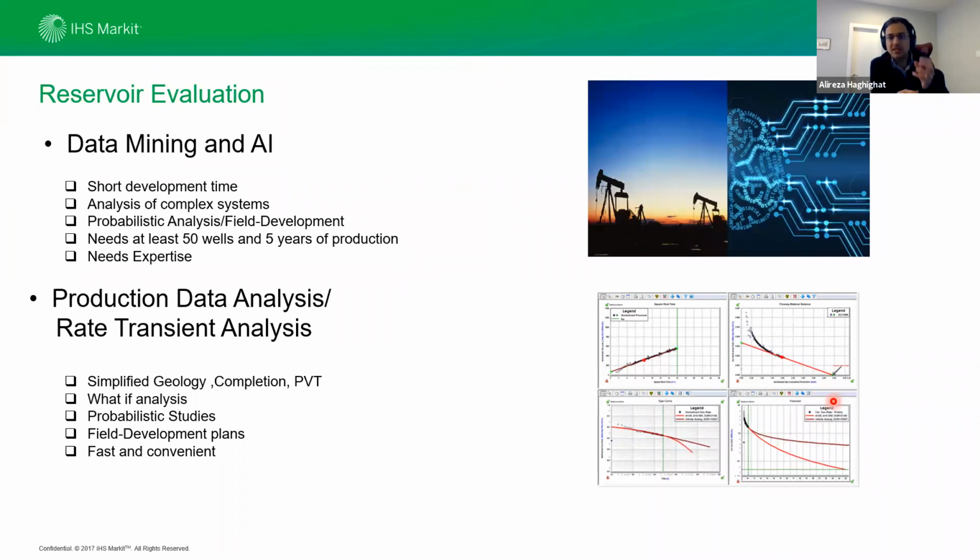So pressure is a signal of your reservoir. If you receive that signal and analyze it, you can characterize your reservoir and understand its characteristics. What is the permeability of my well or formation? What is the drainage area of my well? How much is the well draining? All of these things can help you to understand your well and reservoir.